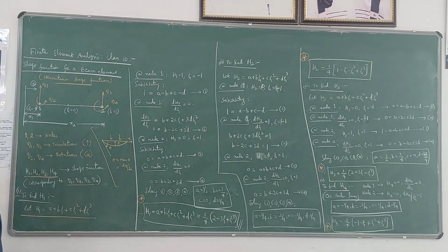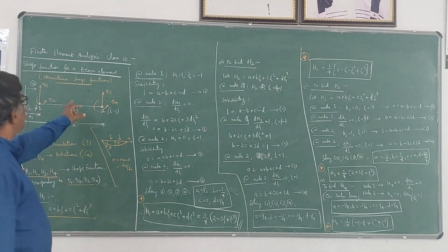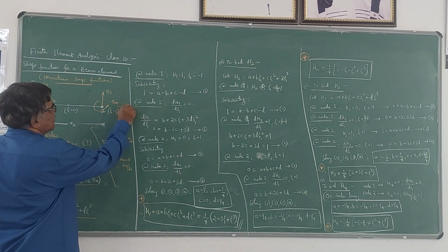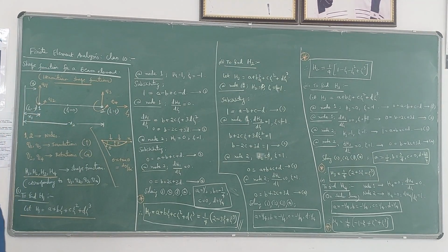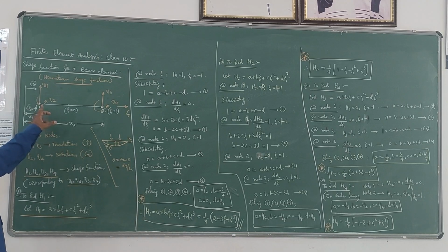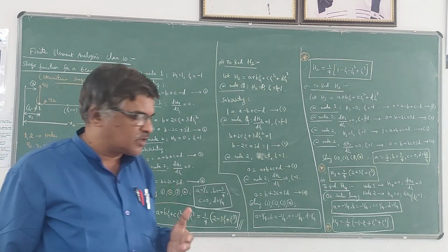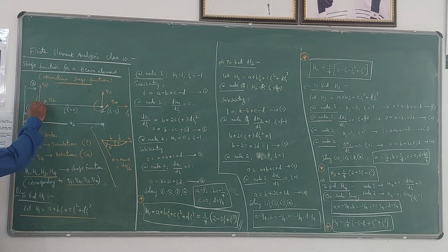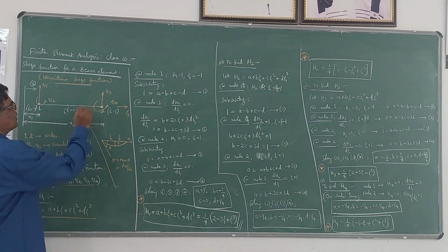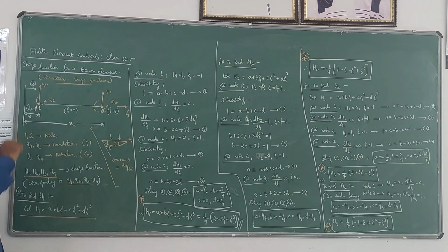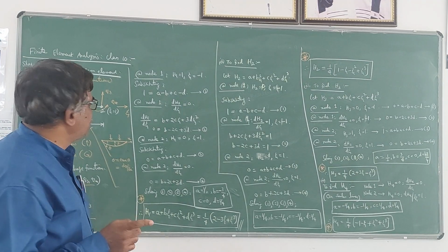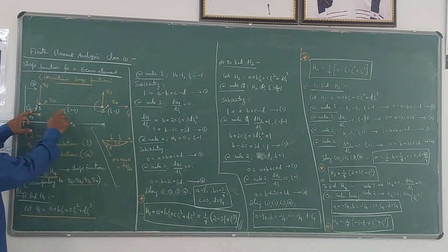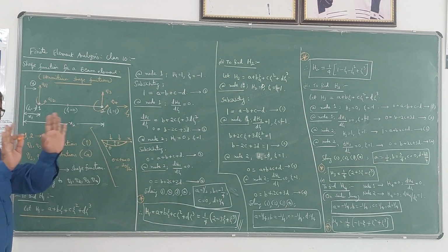I am going to use a natural coordinate system. Beam is a one-dimensional element here, so only zeta will be there as the natural coordinate. You know that the maximum and minimum values of the natural coordinate are 1 and -1. I will take the zeta value as -1 at this node and +1 at this node. Naturally, at the center of the element, the value of zeta becomes 0. So at node 1, zeta is -1. At node 2, zeta is +1. So they are the boundary conditions.